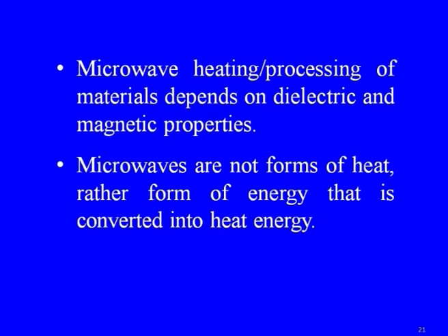Microwave heating, which we also call microwave processing of materials, depends on the dielectric and magnetic properties of the materials. Microwave heating is not only the processing. In certain cases, like chemical processing or some polymeric processing, it does not necessarily result in heating. Like certain chemical processes, the reaction rate gets enhanced because of exposure to microwave energy.